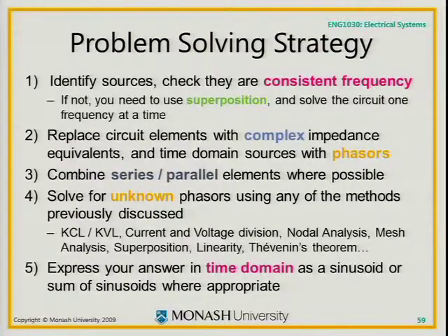So here's essentially the problem-solving strategy with this. If you've just got one frequency in the circuit, that's fine. You do this J omega L, 1 on J omega C everywhere.